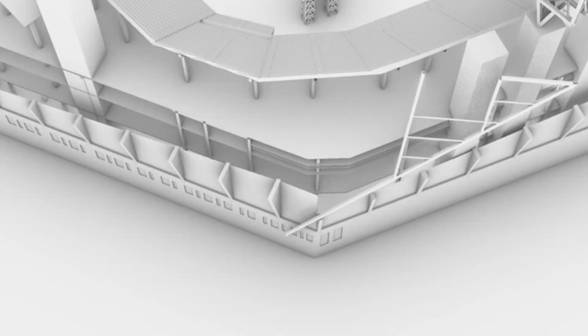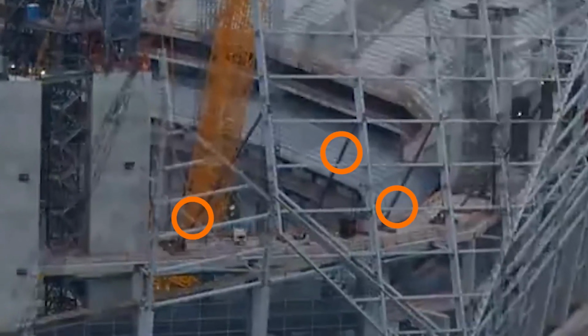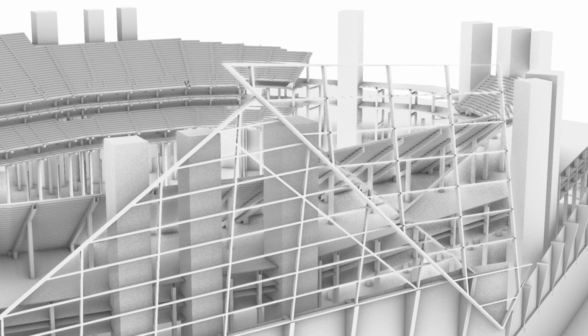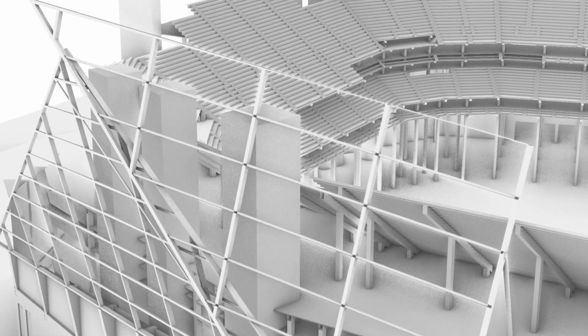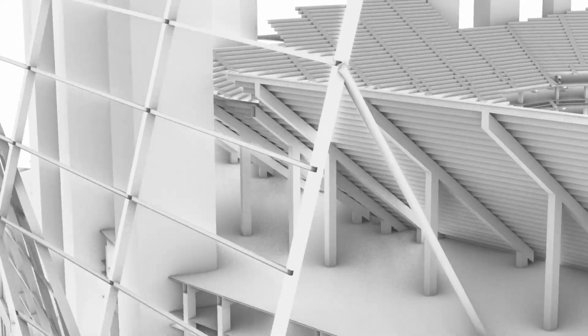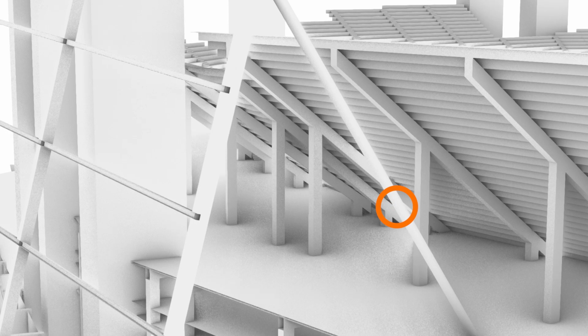First, vertical members were installed to define the initial frame. Then, horizontal members were connected between the verticals to form the triangular geometry. All members were joined on site with bolted connections, and partial field welding was added at joints that required high rigidity. In the earlier stages of construction, when the facade could not support itself, temporary support structures were installed to stabilize the frame until the structure became fully self-supporting.